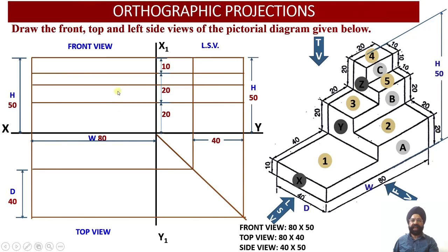So these are three projection lines we have drawn corresponding to top surface of A, B and C respectively. Now next you see here, this is our lower block. Now in the lower block we are going to get this height of the lower block left section over there. This is equal to 10 millimeter.